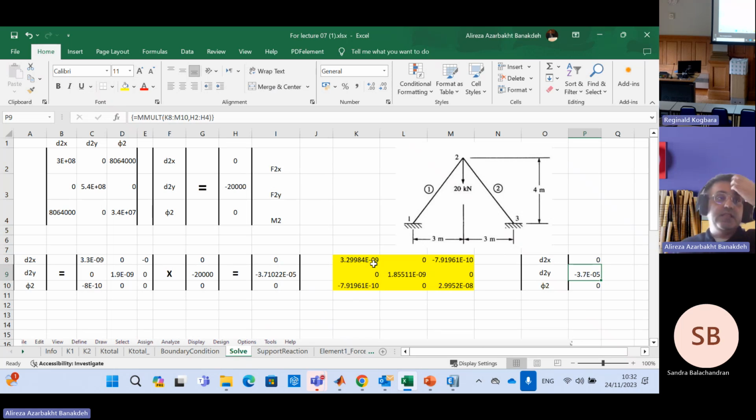That's something to be studied in your coursework, and keep in mind that ETABS always provides you with Timoshenko theory, which is the more correct one. So the benchmark to be compared is ETABS. When you solve your coursework based on Timoshenko, you should anticipate that the results of the Excel and ETABS would be in agreement.